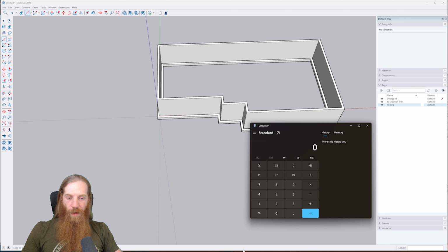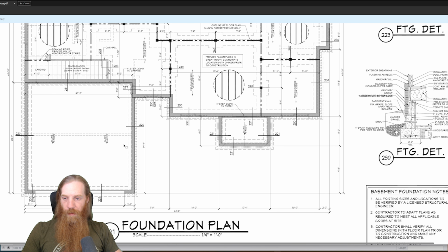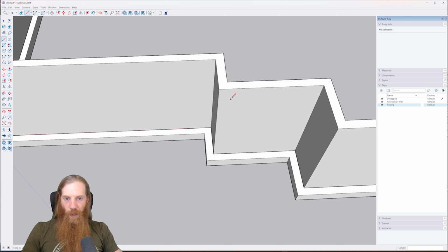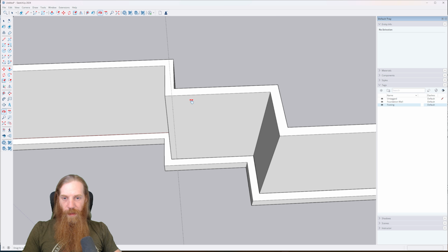So if we have exterior dimensions, maybe we just go with the 22 foot 2. I don't know. No, I tell you what I'm going to do. I'm going to figure this out by marking our point 6 inches in from here, right? Because we want to try and line it up with this wall is the idea here. So we're going to do 6 inches. But see, and that's why they have it set up differently in the plans, I think. So let's cancel that. We're going to go the full 8 inches. So 8, put a reference line right there.